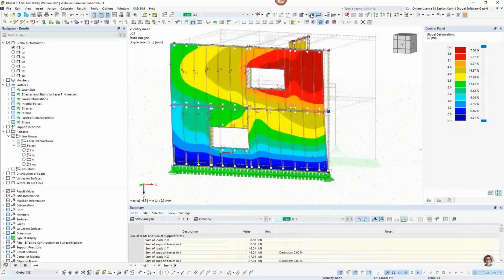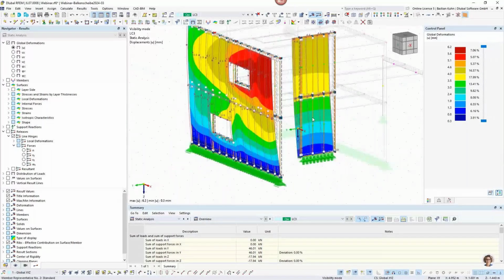So masses maybe also a good point. One other advantage of using such a 3D object is that you can use the stiffness of the timber frame wall similar as CLT for every calculation. So also for your dynamic analysis, you can create response vectors and use it for this. Okay, and you see in here, this is now quite similar to what we have before. We have the deformation, we have the inner forces of the beams, and can do the verification, of course, on it.